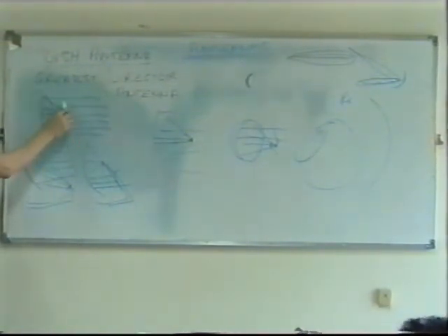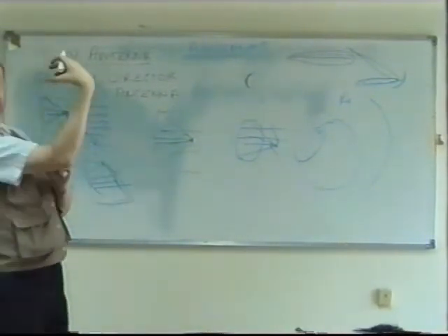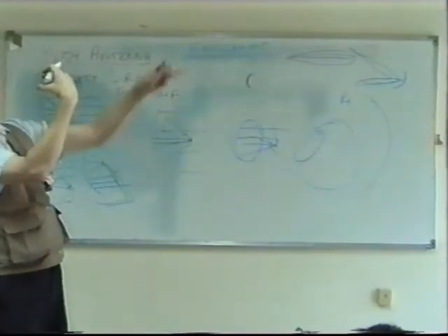Anything in front of that wave, anything that goes in front of that beam, is going to cause small amounts of energy, if it's a transmitter, to be radiated in other directions. And that will produce a side lobe. Now, in actual practice, of course, we can't just have a point there with nothing on it. It's got to be physically connected to something. So we usually have some metal structure here to hold it. In the case of, for instance, a TV receiver, we call it the LNB, don't we? And that's right in front of your dish. So you're going to have reflections off this